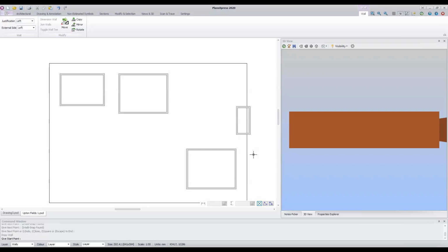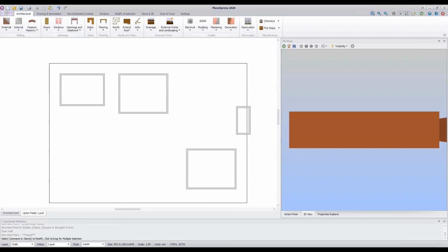So you can pick up again if you're partway through a wall, you make a mistake, you need to finish what you're doing and then pick up the wall specification again and carry on. That's perfectly doable. Use the right click to start drawing walls of the same spec. Make sure you're in snap mode so you can click onto the snap point on the existing wall and continue onwards. Of course, you could then carry on using your arrow keys if you wanted to enter the dimensions that way. Okay, so the escape key drops the tool you're using. So I'm going to press escape now because the software is ready to draw more walls. So I'm going to press escape to stop and right click to redo something of the same spec.